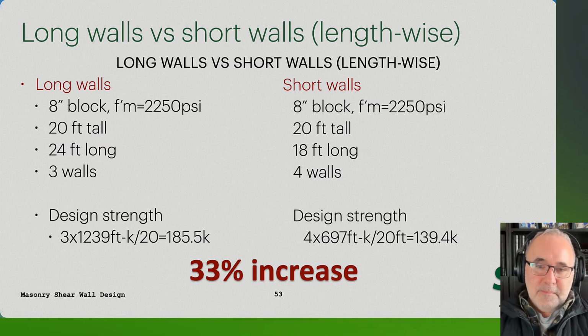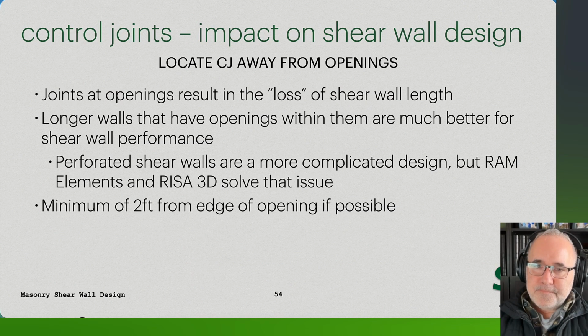Now, maybe for the design, it's shear that controls, and then obviously in that situation, they're going to have very similar shear capacities just due to the exact same length of wall. So it's when you have a moment capacity that you're considering. Taller walls certainly have more of a moment demand. Shorter, more stout walls are going to be more of a shear load dependent design.